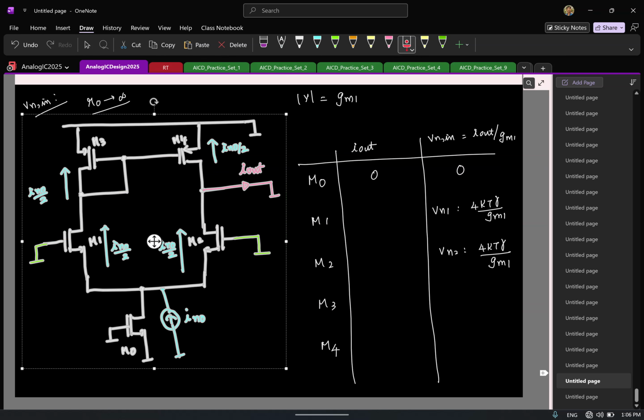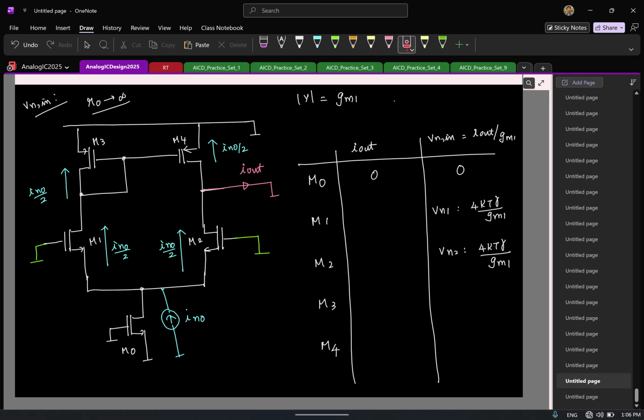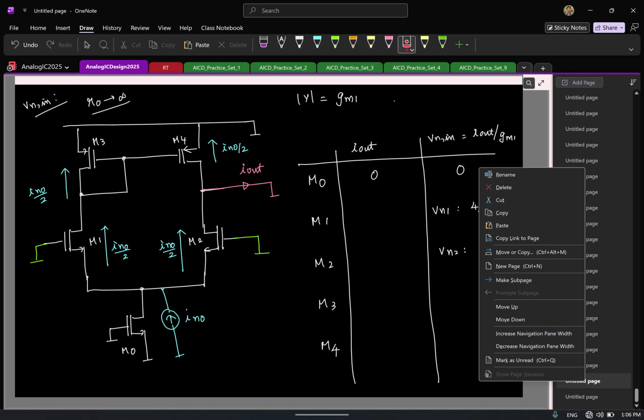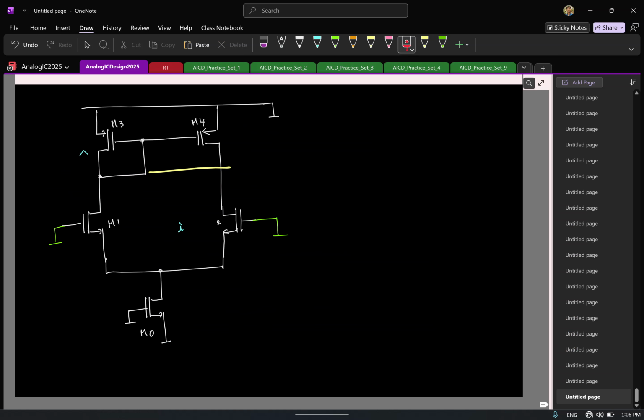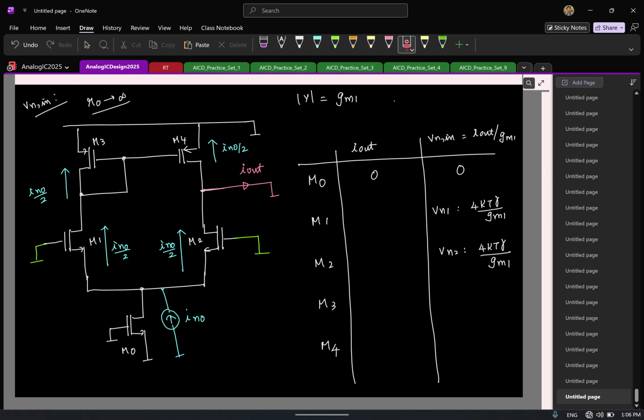So here once again you see you have a similar thing happening. You have a common mode excitation injected onto the common node, and because this has an infinite common mode rejection, this noise current source will not appear at the output. But if that is not clear, at least this expression should be clear, right? Half the current flows here, half the current flows here. Because these two currents are equal, the output current is 0. Cool. So now let's do M3, M4. That will wrap up.